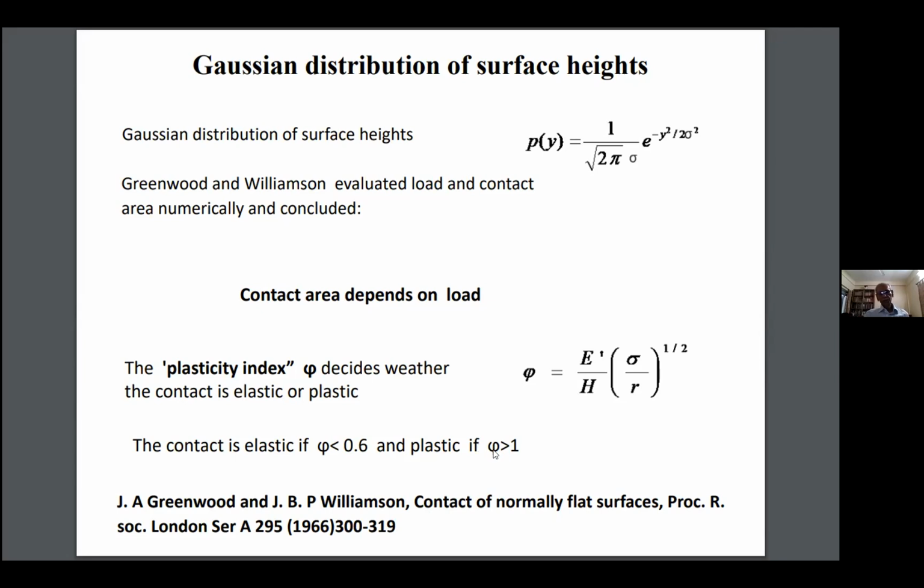This is a wonderful way of solving a big problem. Because when two rough surfaces are in contact, we do not really know whether they are elastic or plastic. And depending on that, many problems can be solved. If it is plastic, then we know that the surfaces will not regain, and hence the contact will remain where it is.